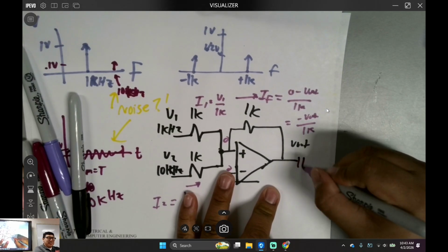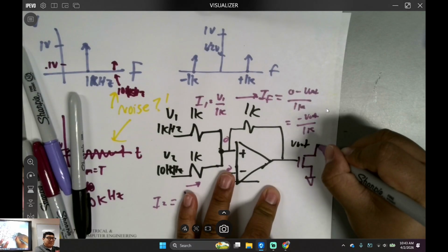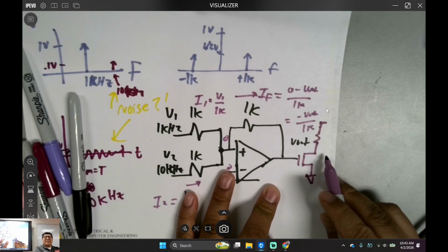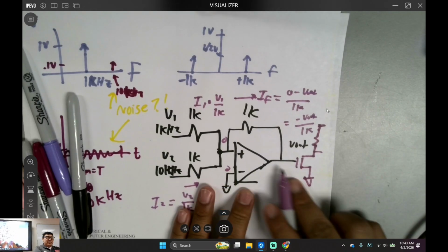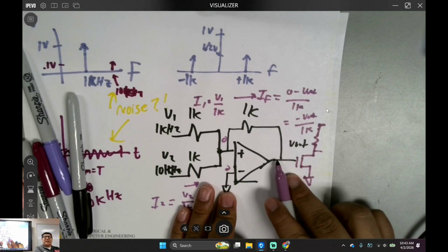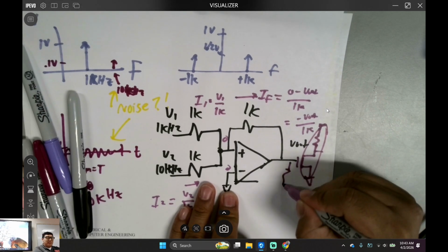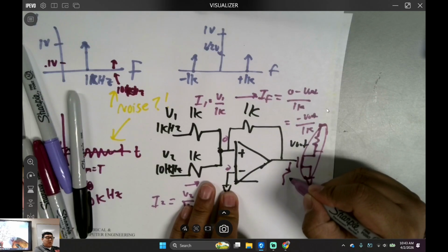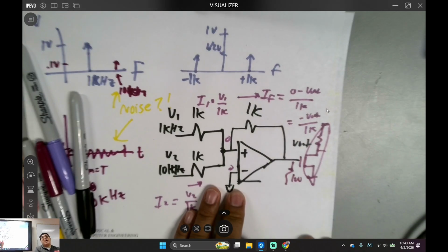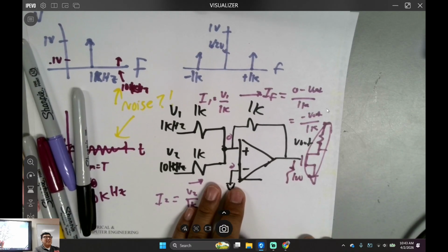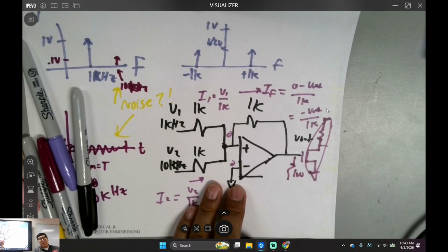Like here's your NMOS, and build an amplifier right there. Because this right here amplifies the voltage, right? But if I put a resistor here, like, I don't know, 100 ohms, it's going to kill the output. Can you agree with that? So we need to drive that with a current driver.